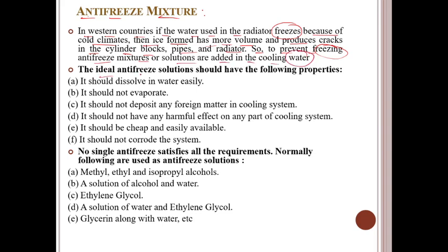An ideal antifreeze solution should have the following properties: it should dissolve in water easily, it should not evaporate, it should not deposit any foreign matter in the cooling system, it should not have any harmful effect on any part of the cooling system, it should be cheap and easily available, and it should not corrode the system. So these are the properties required of the antifreeze whenever it is added to the cooling water of the engines.